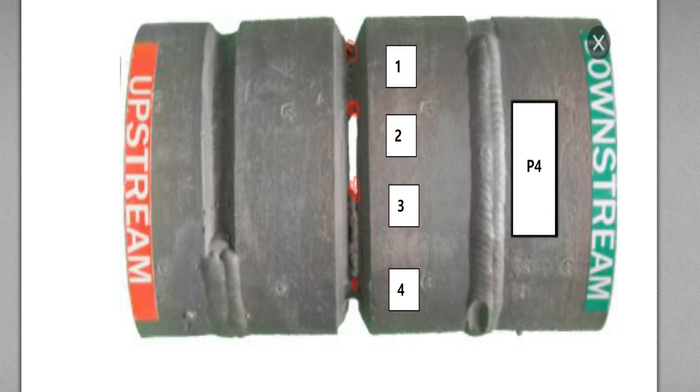These days, in recent CWI Part B questions, you can have the actual questions where you have the tack weld here, but no discontinuity on the tack weld, but here on the bevel surface you have the arc strike.